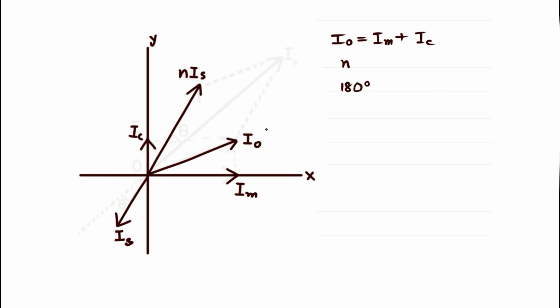So I0 is the excitation current which is consumed to excite the core of the transformer, meaning to magnetize the core along with its loss component. And NIS is the secondary current referred to the primary, or better to say, the NIS current is what actually transforms to the secondary circuit of the current transformer as IS. Therefore, the total primary current will be the vector sum of these two components. Let us draw the actual vector sum of these. This is the actual current IP.